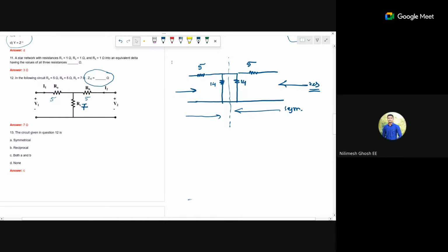The thing is, if a particular circuit is a reciprocal circuit, now you can interchange the load and the input. So if you interchange, your analysis will be much easier. And half of the circuit will behave exactly equal to the other half, so we have to analyze only half. The other half will be predictable for us. We don't have to go through the rigorous analysis of the other half. So analysis of a circuit will be much easier.